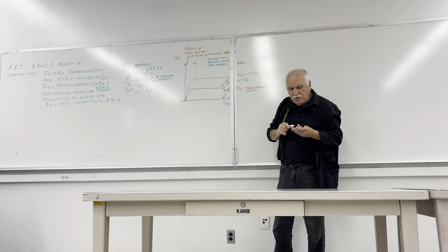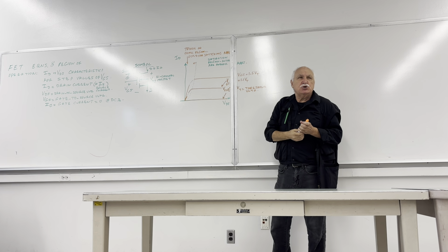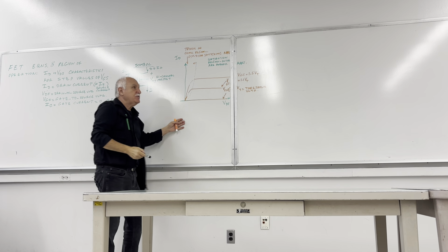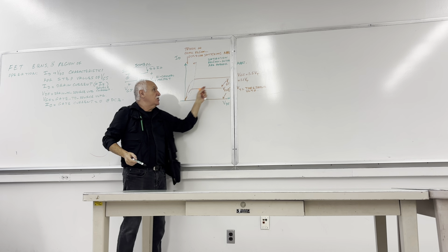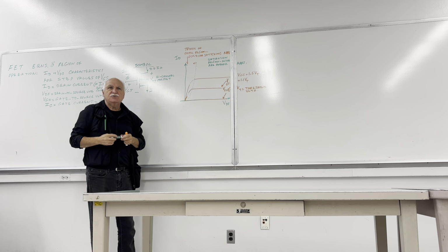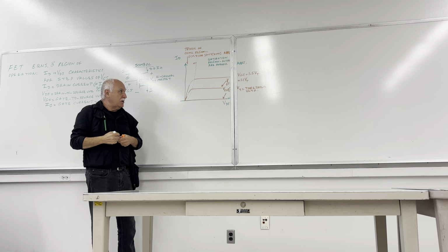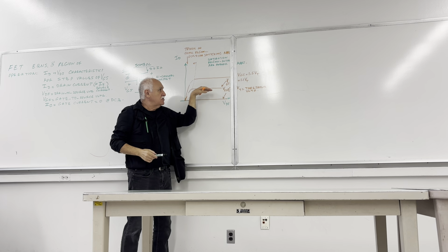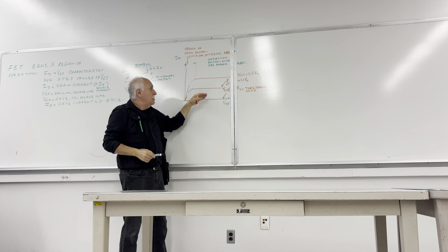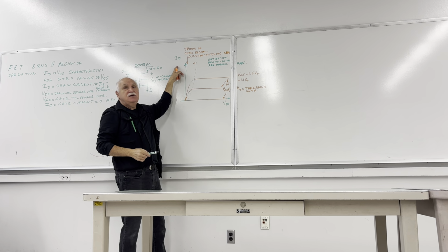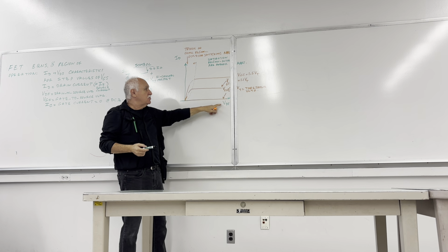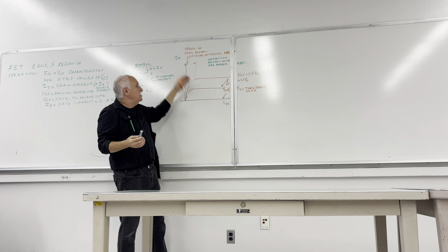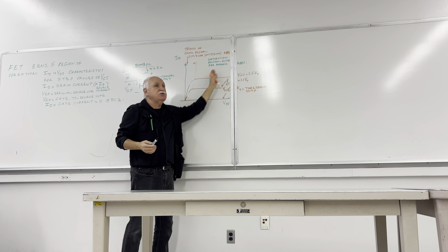However, if you ensure that you're operating in the saturation region where the lines are horizontal, there is another more popular characteristic. Here, when something becomes horizontal in the VDS plane, that means the change of ID with respect to delta VDS is 0. That means ID is independent of the drain to source voltage in here.